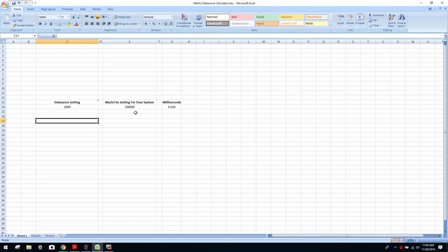Bottom line, when you're dealing with Mach 3 in a professional manner, which most of you are, or looking to start a business, you want a system that's extremely stable. Therefore, the computer I recommend, as in previous videos, is an Intel i5 or i7 CPU. They are multi-core processors, Intel's latest technology. You can go with an AMD multi-core processor, but not from, once again, 1990 or 1995. You want something modern, with a minimum of 8 gigs of DDR3 or DDR4 memory. That's more modern memory, and it will give you the ultimate stable system for CAD/CAM.